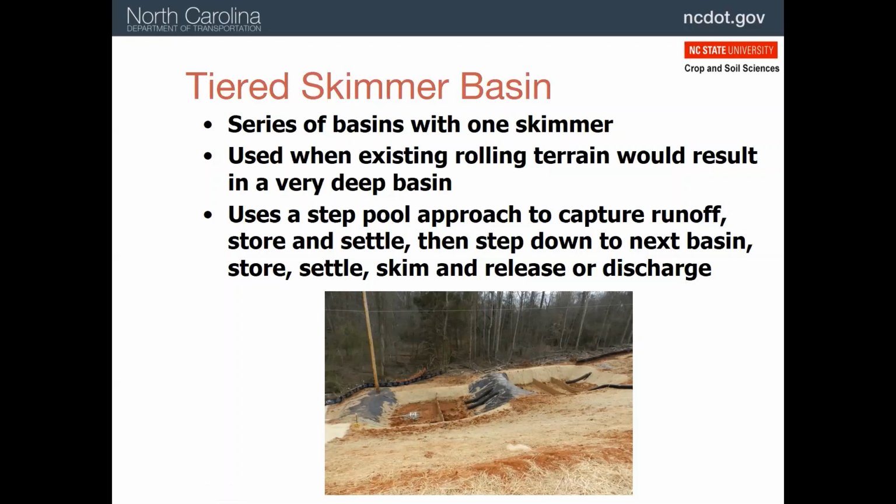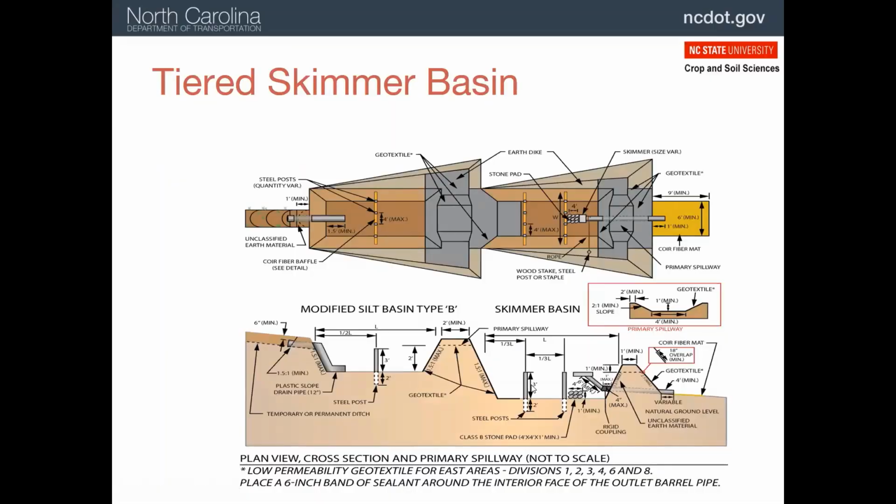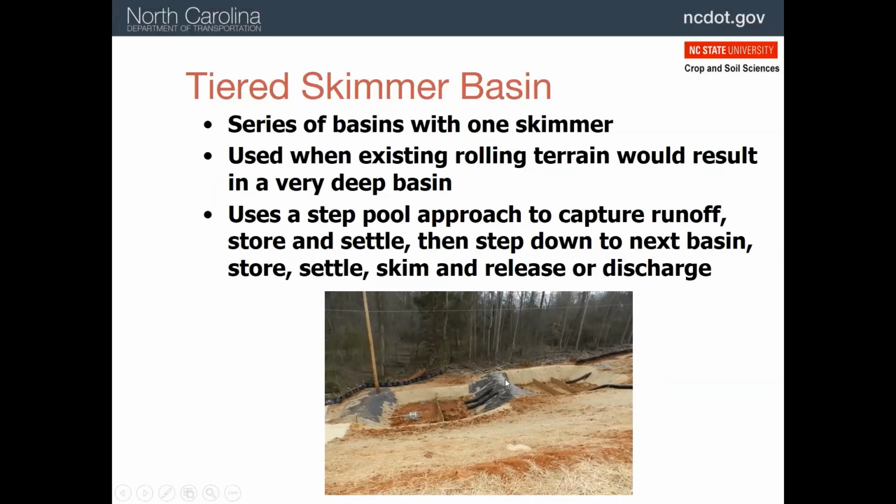Now this actually creates a great situation for treating this water for turbidity. So here we go with this dam. If this is a low point, a weir, we can put flocculant, polyacrylamide, or similar materials here, or we could put them in the pipes. And so as the water moves from the upper chamber to the lower chamber, it gets treatment for that turbidity.